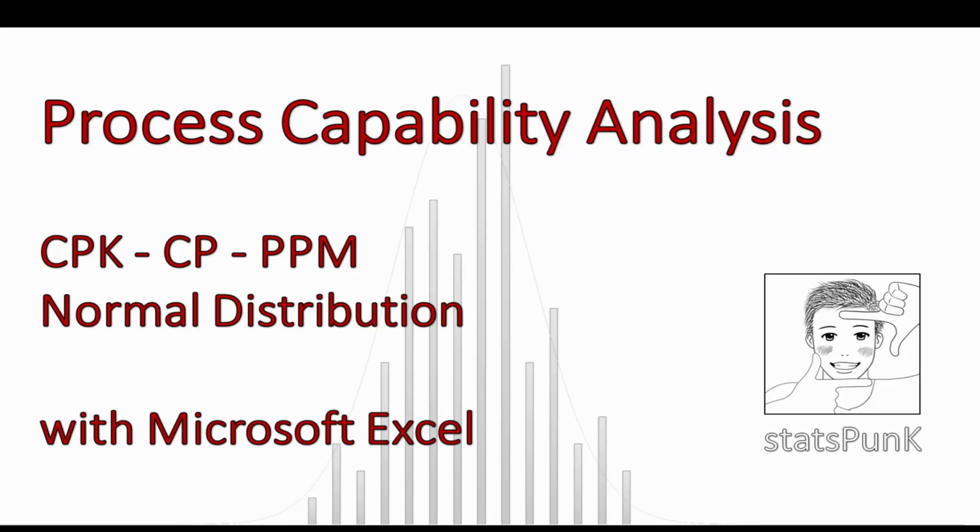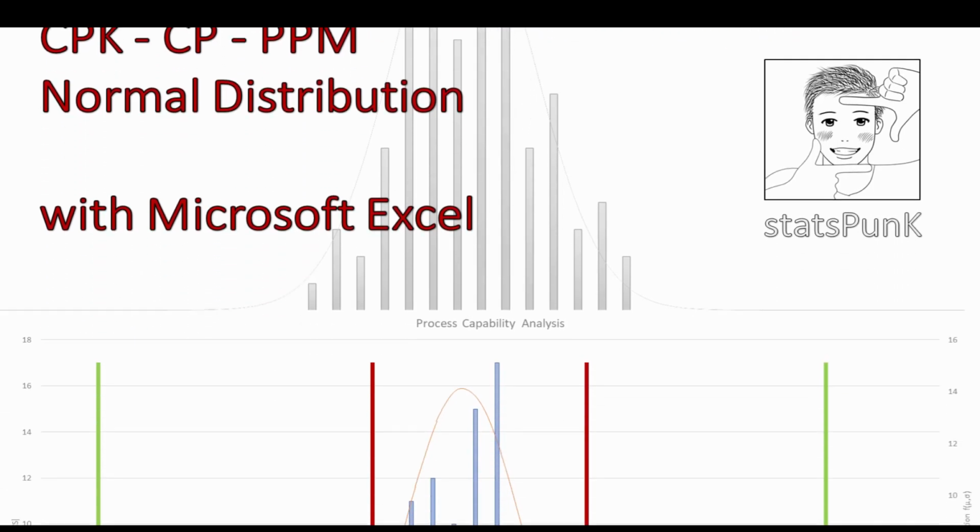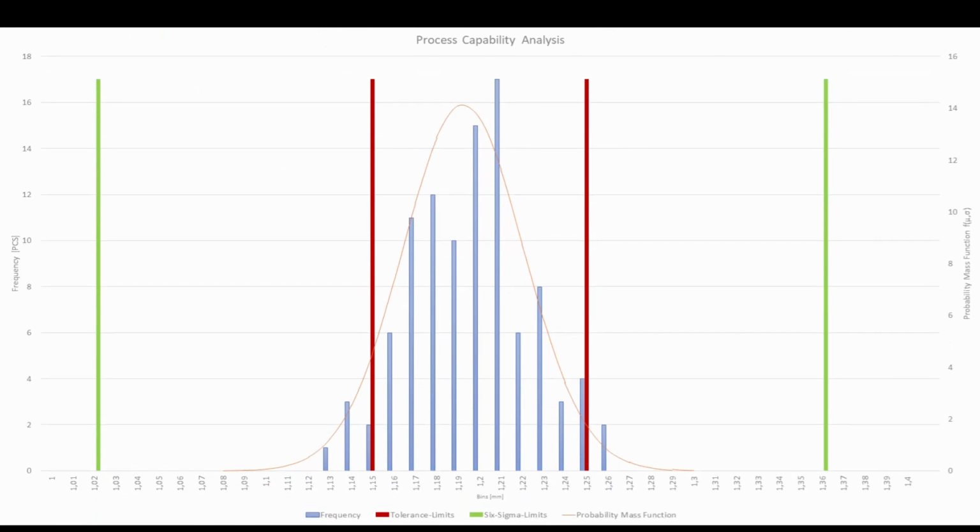We will calculate the process capability from a set of linear measures, which we assume are normally distributed. We are looking for the process capability index, CPK, the maximum possible process capability, CP, and the parts outside of the tolerance limits in 1 million manufactured parts, PPM. Furthermore, we will plot the results with this chart.